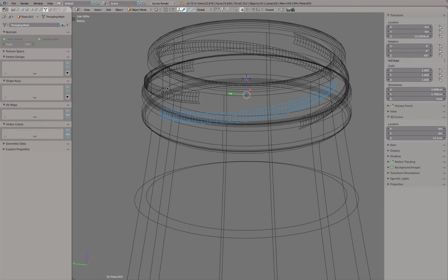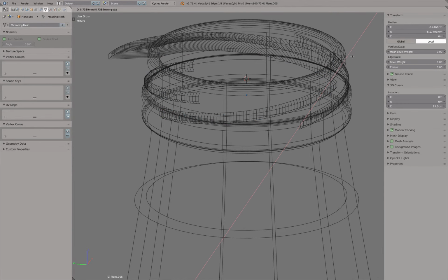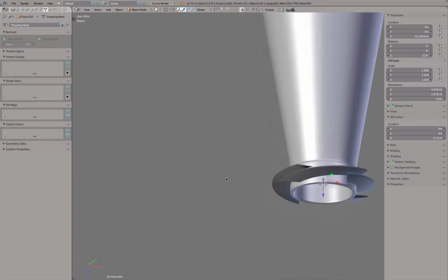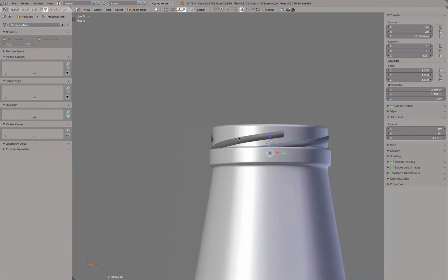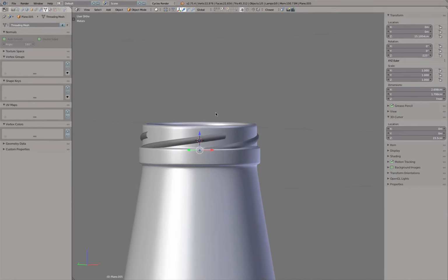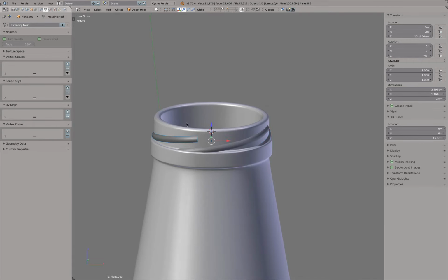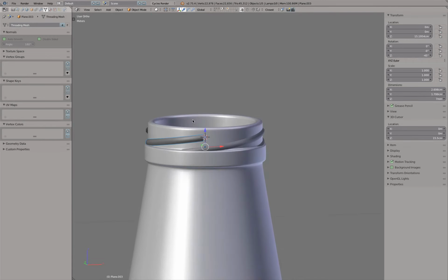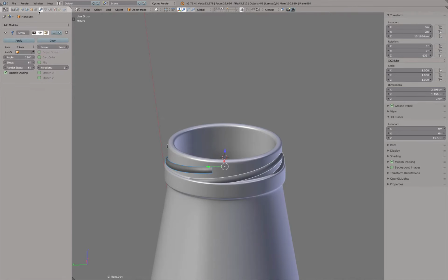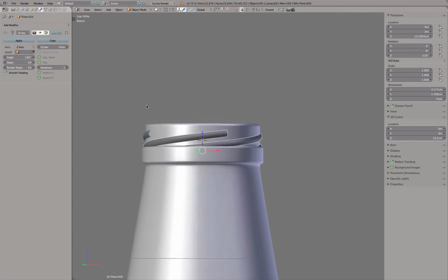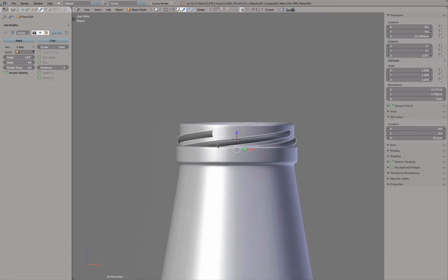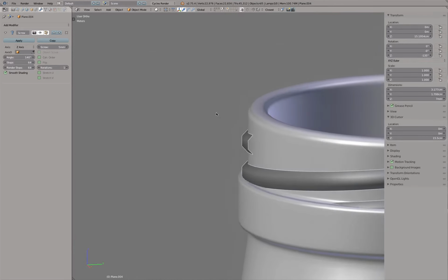So advantage of this is I can select every object and, for example, modify the mesh, and then yeah, all other objects that are linked are updated. Okay, let's undo it. And I would say we are pretty close to maybe start adjusting this a little bit more and sculpting it. Maybe I would like to change the radius a little bit more. Instead of 120, Alt click 140. Yeah, we have a little bit more overlap here, a longer distance, so we can have a better and tighter fit. That is good.